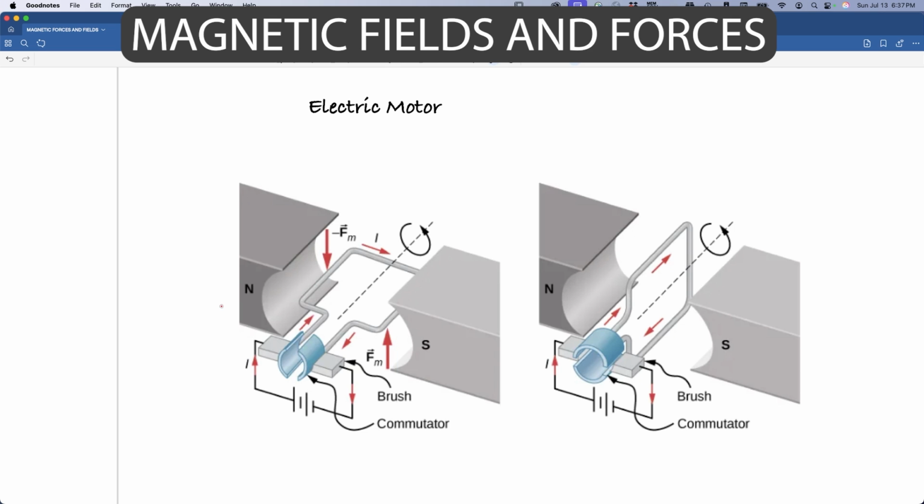Now the arrangement has what's called a split ring, touching against brushes, metal, and this is carbon usually. Now the idea is that even when this rotates, we need to have a contact all the time for the current to flow. Otherwise these cables will get entangled. I suppose you know that. So that's why that's given. And you see that the coil begins to rotate. So that's the simple principle of a DC electric motor.